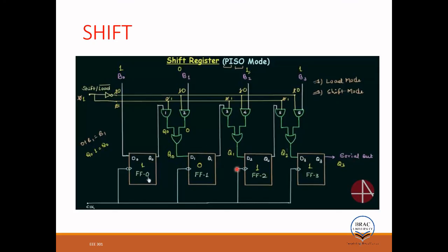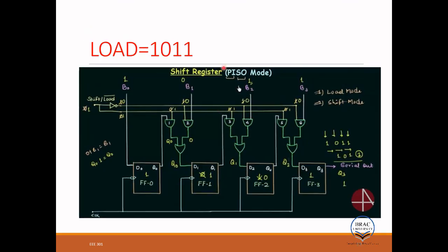If you look here, 4 0s, then 3 0s, 2 0s, 1 0, then all 1s, again 1 0, 2 0s, 3 0s, 4 0s. It's following a pattern actually, right? Okay, so this is a special kind of counter. This is called the Johnson counter.